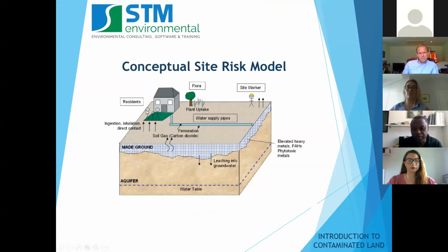Potentially, if you've got buried waste on the site, you could be generating gases which are migrating up into your house, and if they make their way into a confined space, you could get an explosive mixture, which could cause an explosion. You've got contamination that can leach down into the water table, into the groundwater aquifer, not only polluting the groundwater, but also migrating and potentially causing vapors to ingress into other adjacent buildings and properties. So a lot of things to consider when you're looking at the issue of contamination.